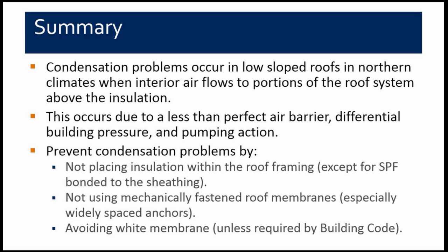If you're using the air barrier, there's a lot of talk about calling it a vapor barrier or vapor retarder. I'd like to make sure we correct that terminology, because the steel deck is a very good vapor retarder. It's not a good air barrier. The rubberized asphalt makes it an air barrier. In the industry, they keep referring to them as vapor retarders, but they're not really functioning that way. The primary thing is to make it airtight. When it's on the top surface, it's easy to inspect. It's fairly easy to make it virtually airtight. You just have to be very careful with the anchors that go in.